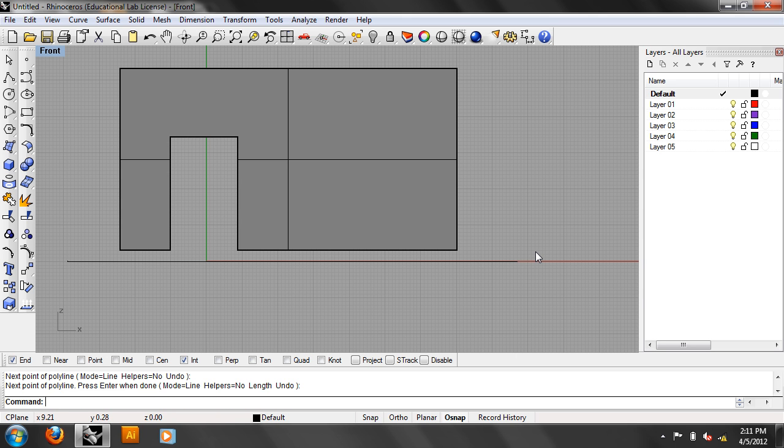Whereas in AutoCAD, yeah, you just grab the end lines and you pull them and they snap and everybody's happy. And in other programs like Studio Max and in Maya, you can just grab points of polygons and just pull them, and it makes total intuitive sense. In Rhino, there's a way to do it, and I'm going to show you. It's a little hacky, but it works for doing a stretch.